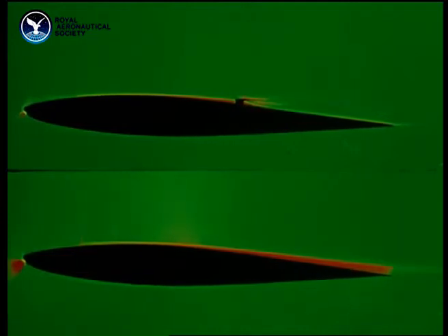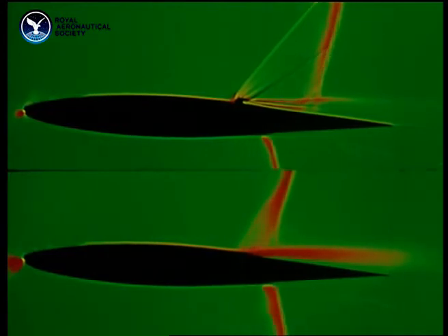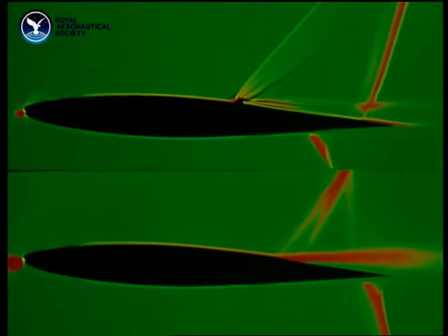These two pictures are of the same aerofoil. In the upper one, vortex generators are fitted. They can be seen jutting out in silhouette. Separation is reduced in the upper picture, and the shock wave is further back. The extra shock wave produced by the vortex generators themselves is a weak one. This principle of reinvigorating the boundary layer may one day be applied by blowing air into it.